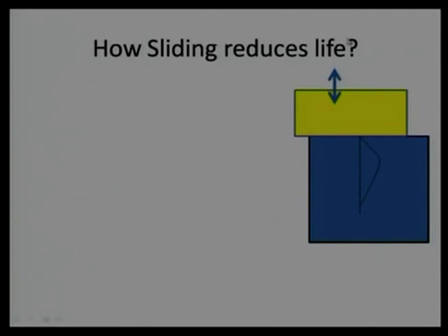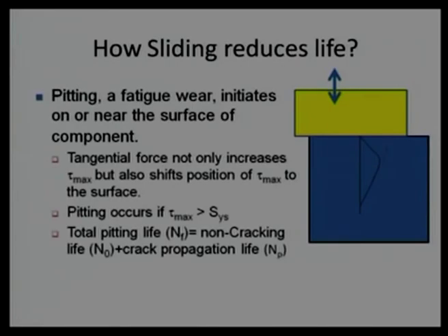Again the same figure is shown, which was shown in a couple of slides previous to this. It says that there is a yellow block subjected to reversible load. Explanation was given why the load is dynamic, and then the blue block is experiencing some shear stress, which is detrimental, or it is creating some problem. It is going to generate some sort of cracks, some sort of voids in the surface, but not immediately, maybe after a number of cycles.